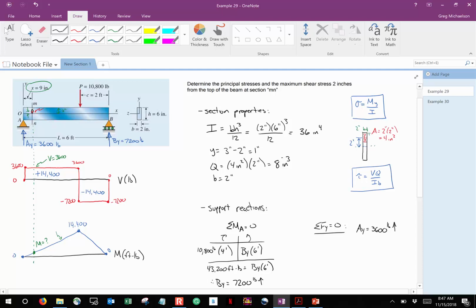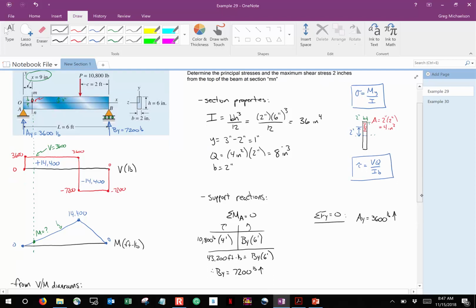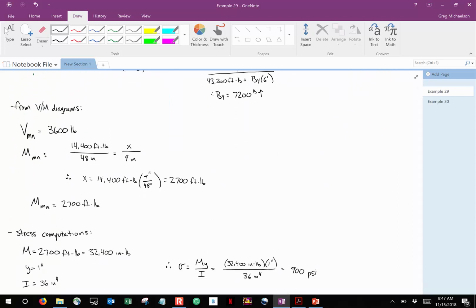And so at the neutral axis we have 0 bending stress, and then above and below we get changes in values. For this beam, remember this beam is going to bend in a smiley face fashion. So in a smiley face fashion, the top is going to be experiencing compression. So you don't really have to worry too much about positives and negatives at this point. However, I do think it's really important to say that this is compression.